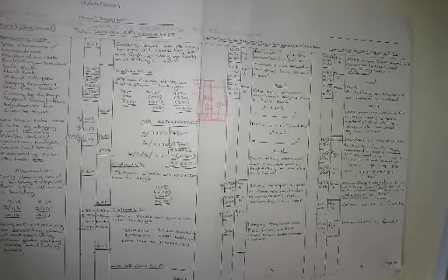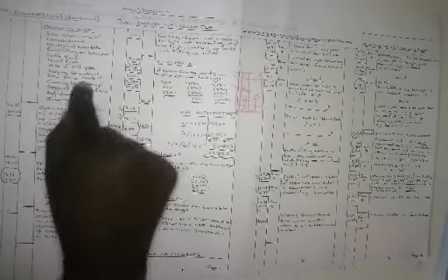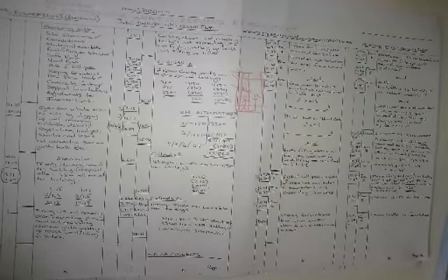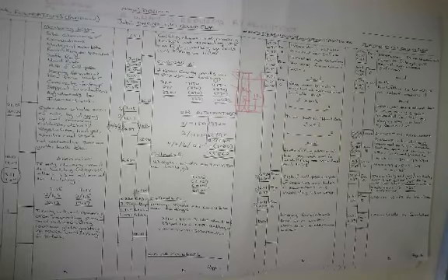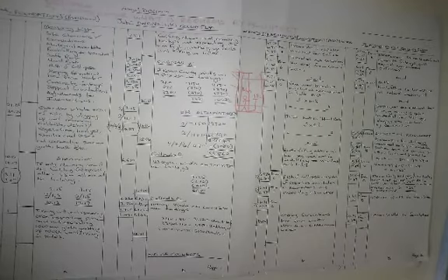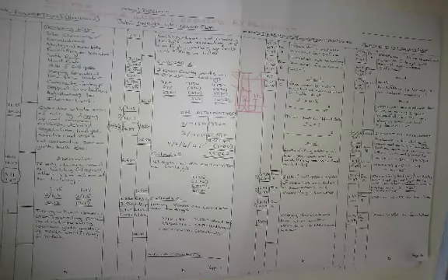I'll send you some literature on risk of collapse. Okay, that's one of the things we need to measure when it comes to excavation and earthworks. So we're still on our measuring list, and then we've got an item called keeping excavations free from water. That item deals with rain mostly, because you've dug an excavation. Tomorrow it rains, you come back, it's full of water. That's not desirable from our point of view.